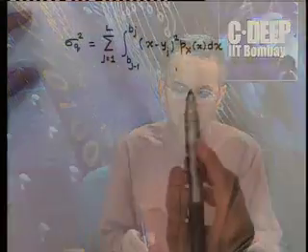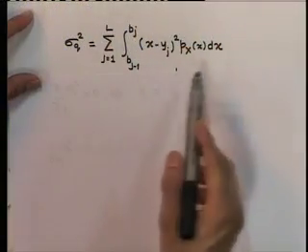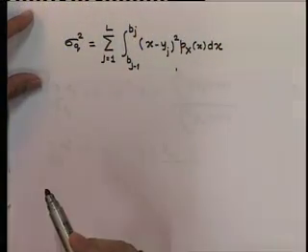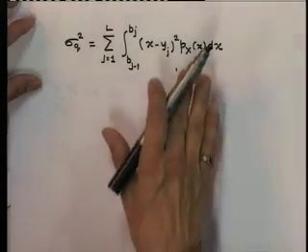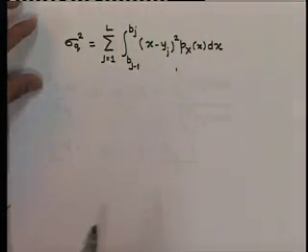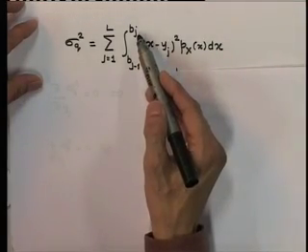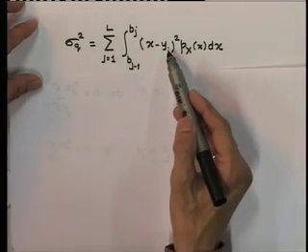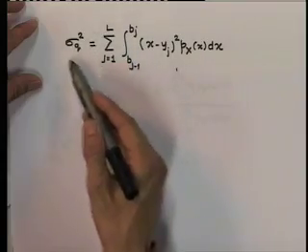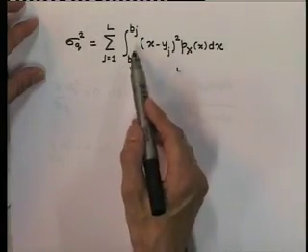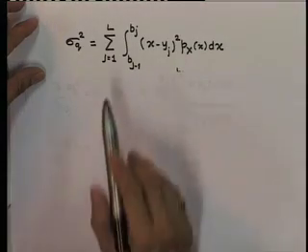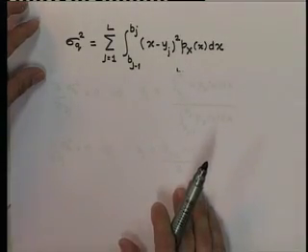So, if we have a probability model for the source, then a direct approach for designing the best non-uniform quantizer is to find the bj's and yj's that minimize this equation. Now, to obtain bj's and yj's, we can follow the following procedure.